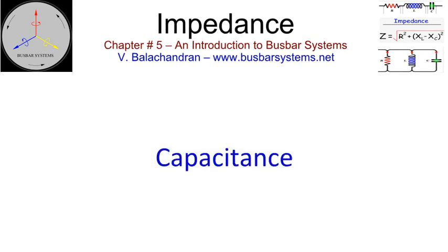Capacitance. As mentioned earlier, the capacitance in a busbar system with air insulation in isolated phase bus, segregated and non-segregated phase bus, high voltage open bus, and high current open bus in furnaces is literally of no consequence. There is, however, capacitance of some significance in sandwich bus and low voltage cast resin bus, where the conductors are close to each other. Shielded conductors in solid insulation bus and medium voltage cable bus also have significant ground capacitance.